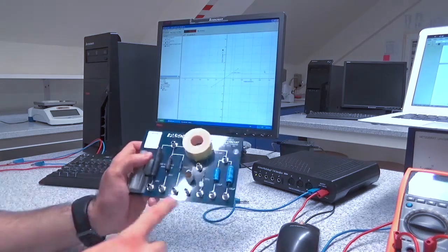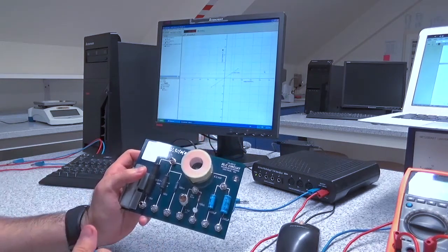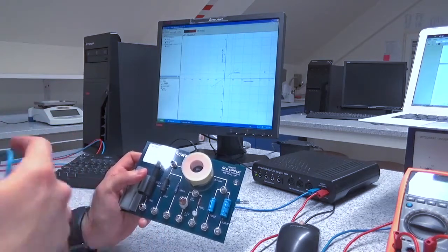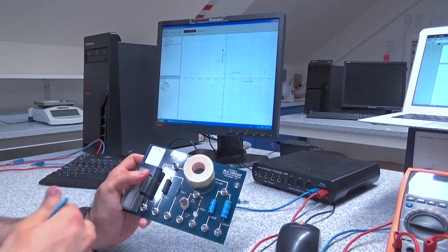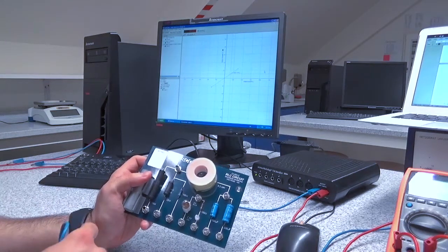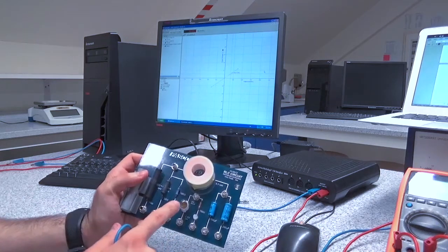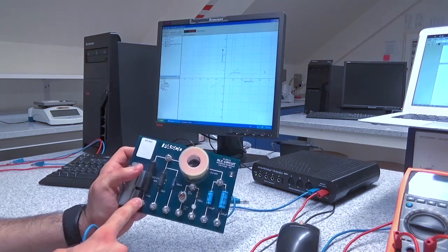For that matter, we are going to be studying the following light bulb in order to study a non-ohmic device. So you are going to be studying how the voltage and the current is going to be changing across that light bulb, and the relationship between them is going to be forming a curvilinear shape. So they ask you in that part to connect the light bulb in series with a 10 ohm resistor, and both being connected to the output of that power supply.